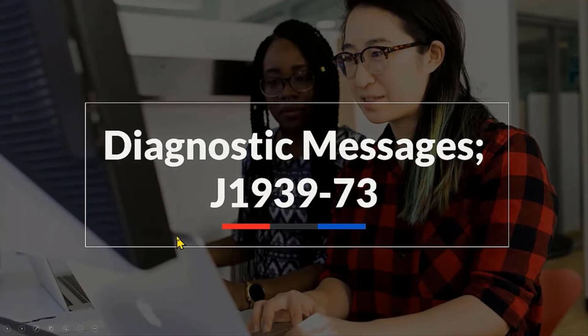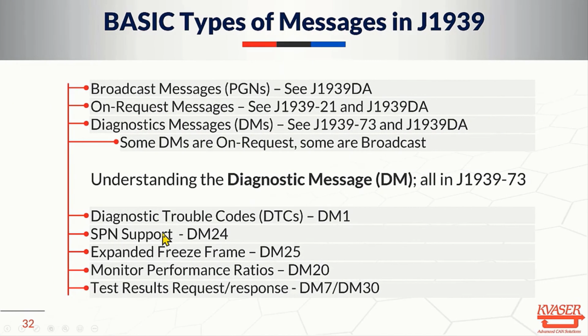We can quickly move on. Diagnostic messages. I'm going to give you a third example here in a bit. So there are broadcast messages, on-request messages, and diagnostic messages. Some diagnostic messages are on request, some are broadcast. Understanding the diagnostic message is pretty much all part of J1939-73. Here are 5 examples of diagnostic messages.